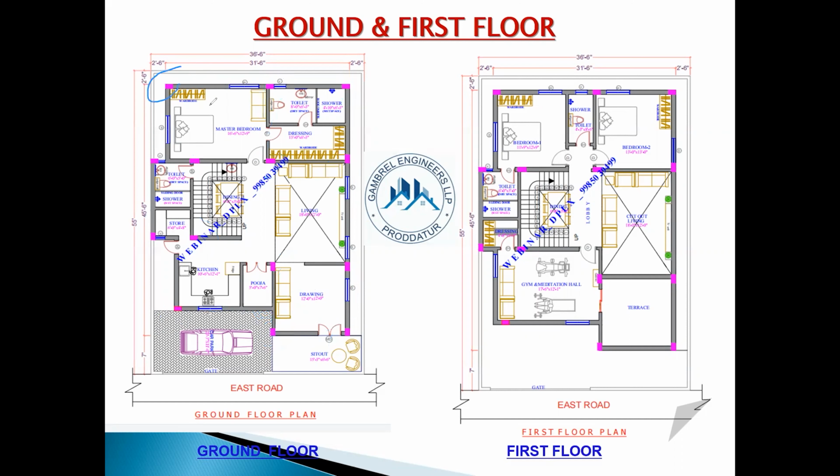Now we know all these column positions; the reasons are in fact guidelines for keeping these column positions. Fine. And next is here. Now why are we keeping this column here and then here? When you are running this beam here, somehow this beam also needs additional support. Though the distance between these two columns is a little lesser, we need to provide this column because we are not left with any other option. We have to keep this. If we keep this column here and the column is here, we are going to run this beam like this and like this, right?